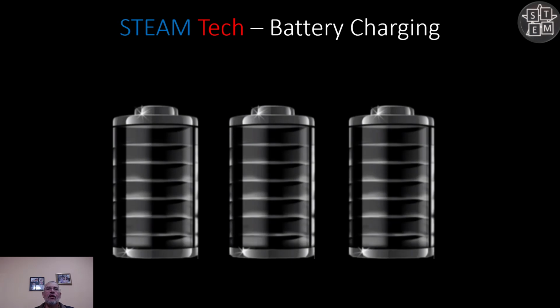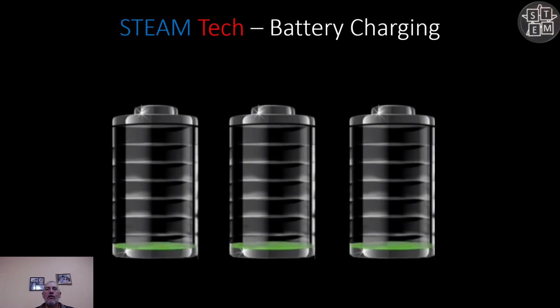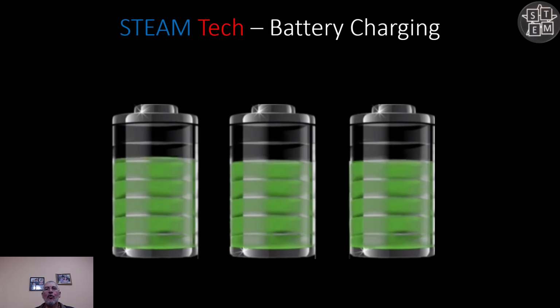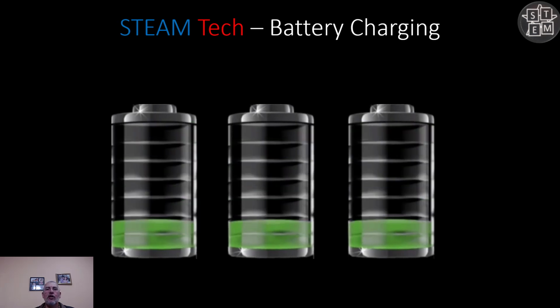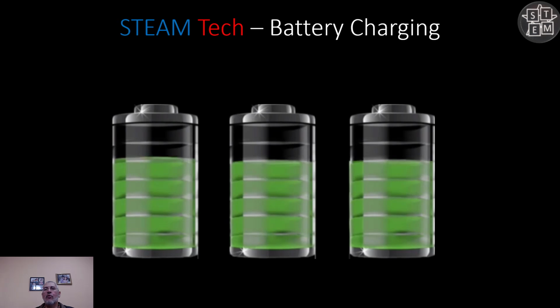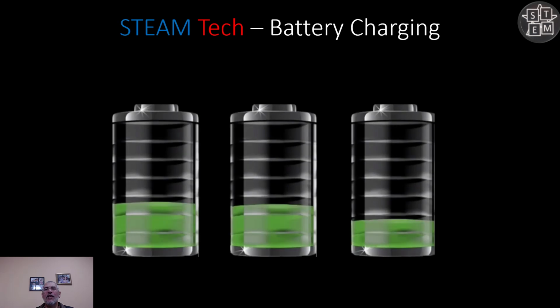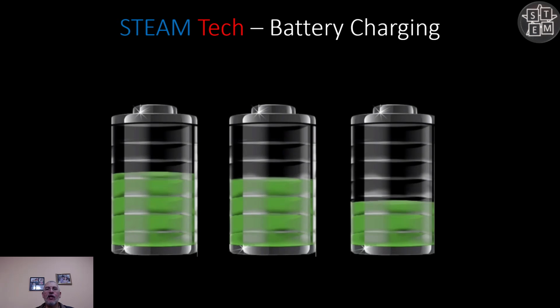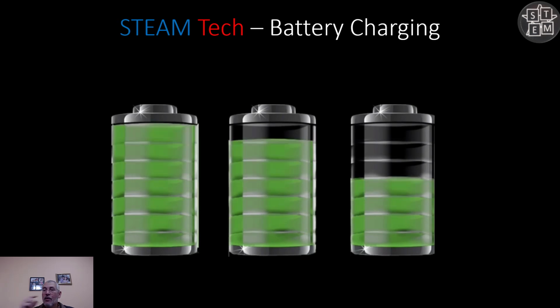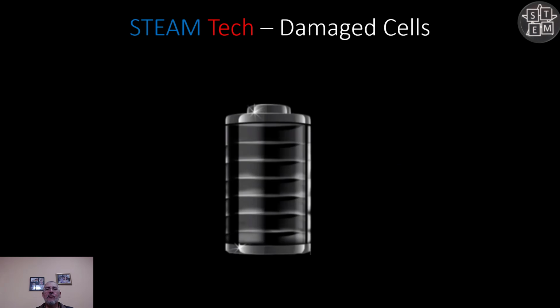discharging percentage. So let's look at a scenario where all the batteries are uniform and they're charged equally, discharged at the same time equally. But the problem is, if you overcharge or over-discharge them, it can cause problems. Some batteries, because of the nature of the chemical solution and electrolyte they have, might not be charged equally. So when you charge them, you might have even charging and uneven charging, and that can cause a problem because you continue charging the batteries and you might damage them.